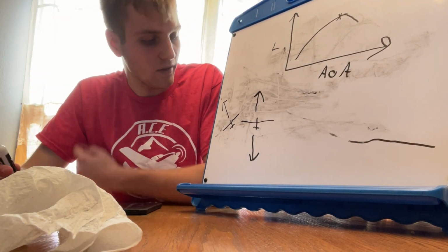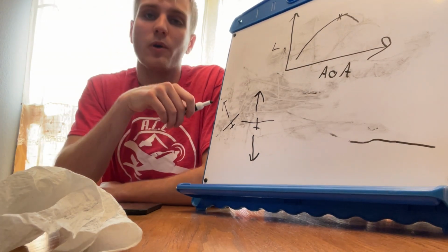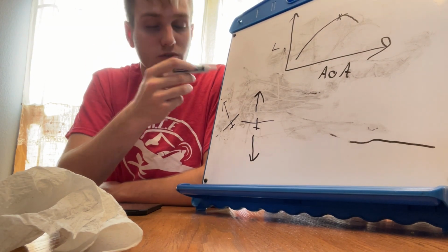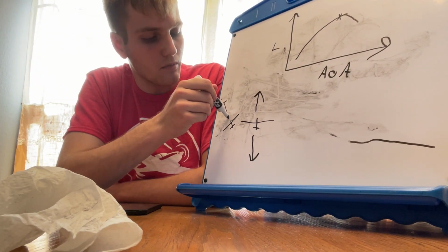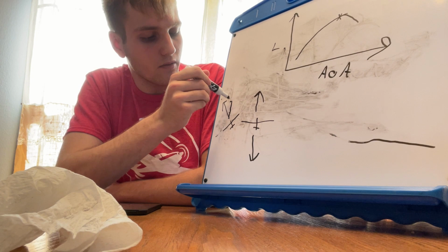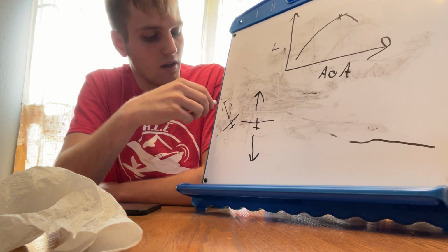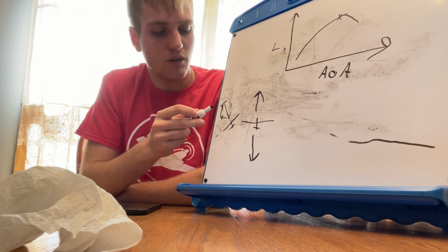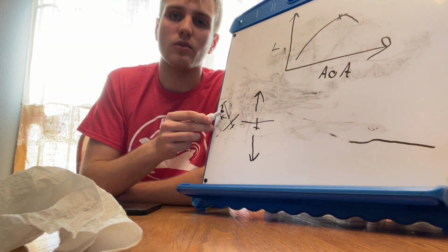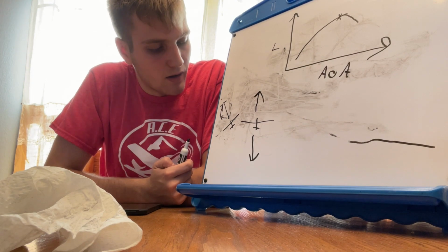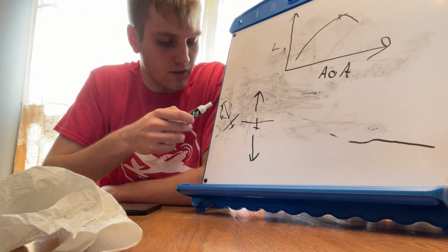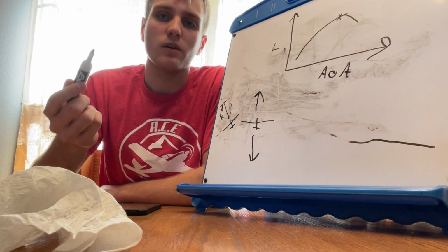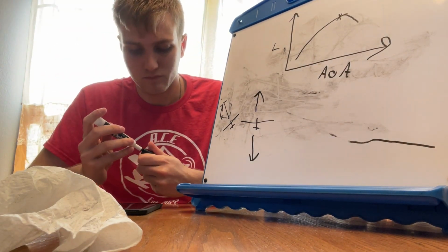And so now let's think about this. We now have less vertical lift because of trigonometry. You'd have the vertical component here, the horizontal component here. So the lift you're generating up is less than the total lift. Altogether, the vertical lift is less than the total lift, and the horizontal lift is less than the total lift. But that means we've lost some of our vertical lift when we're in that turn.